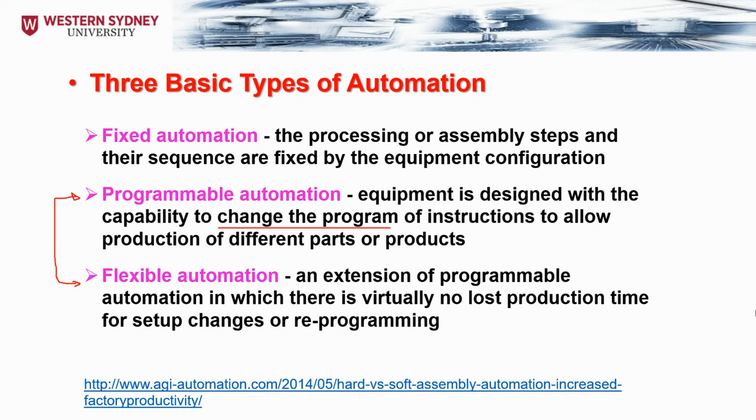For example, all the parts are manufactured from the same block, similar to the one we use in the lab, which is 100 by 100 by 20 millimeter thickness. So the same setup is used, with no need to make any changes. We're going to have a robotic arm which picks the part and puts it in the machine instead of using a manual setup.